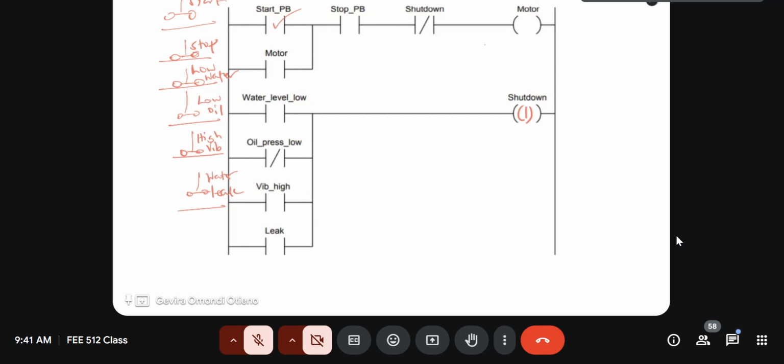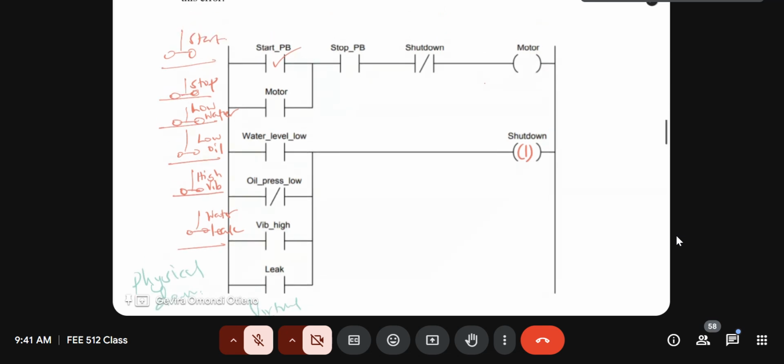Meaning, if you combine the condition of the physical device with the way the virtual device is connected, then it would lead to a logic 1, because the shutdown conditions must be met properly. If they're not connected properly, then the shutdown will not be engaged properly, because whatever has been connected in rung 1 is a typical latching circuit. So there's nothing different or weird there.